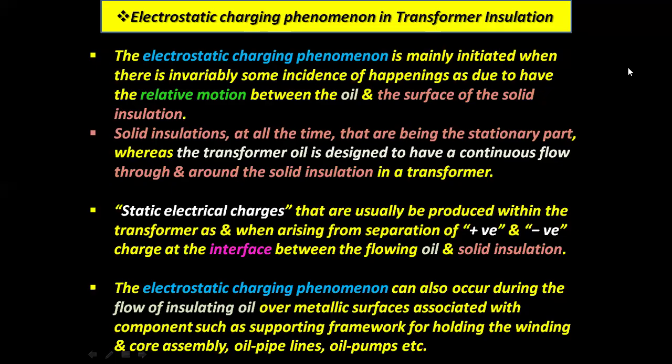Static electrical charges are usually produced within the transformer, arising from the separation of positive and negative charge at the interface between the flowing oil and solid insulation. The electrostatic charging phenomenon can also occur during the flow of insulating oil over metallic surfaces associated with components such as the supporting framework for holding the winding and core assembly, oil pipelines, oil pumps, etc.